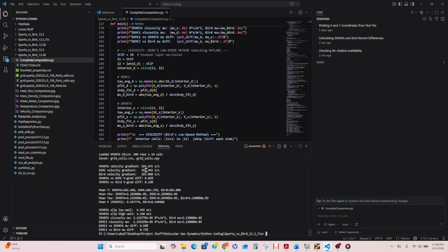All right, so here's where I've done some comparisons. So we start looking down through there, and our velocity gradient is real similar to what Bird stated his velocity gradient was, and what my MATLAB code produced. Start looking at the temperature; it's all really close. The density is all really close. Shear stress, all really close. One thing we can see is that the mean pressure that SPARTA produced is very close to what Bird stated in his text, which is 0.54 or 0.55 Pa.